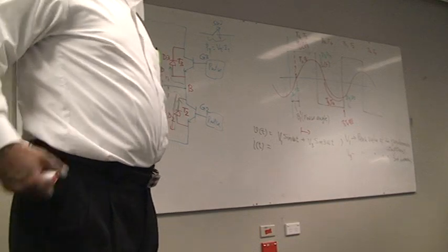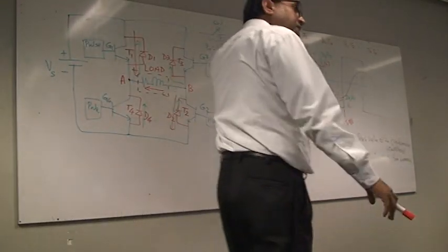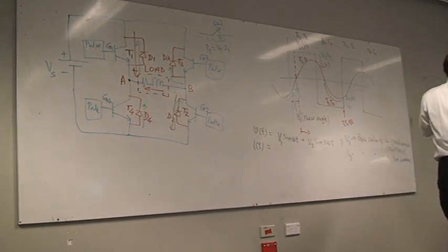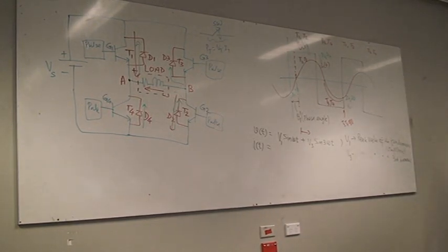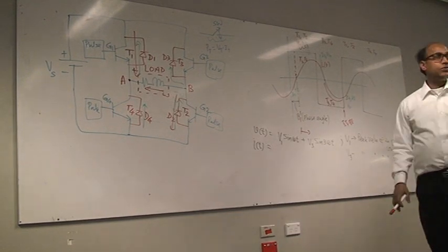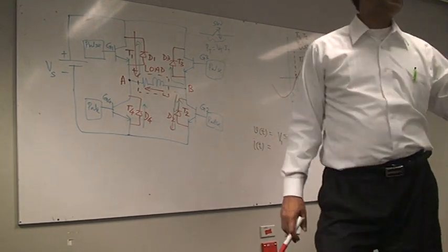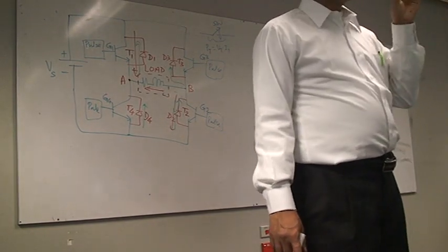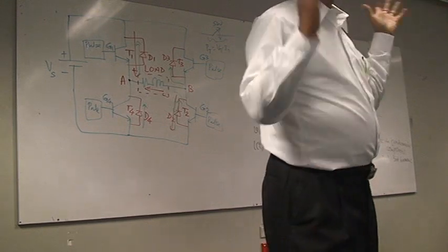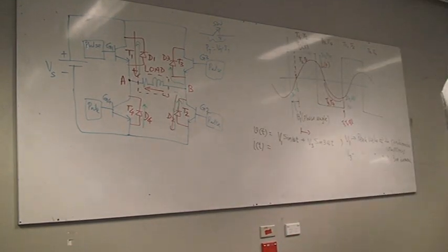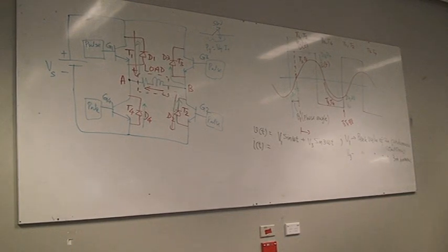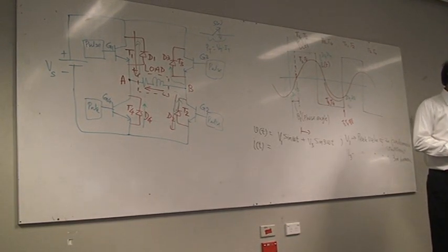This is like two sources, okay? In the first year you did EE 150 that if you have multiple sources in a circuit, you use the superposition theorem. Remember? The superposition theorem tells us that you can analyze the response in the circuit due to one source at a time, and then you superimpose all of them. The assumption is that the other source should be replaced by its internal resistance. If the internal resistance is 0, you can replace it by a short circuit, isn't it?